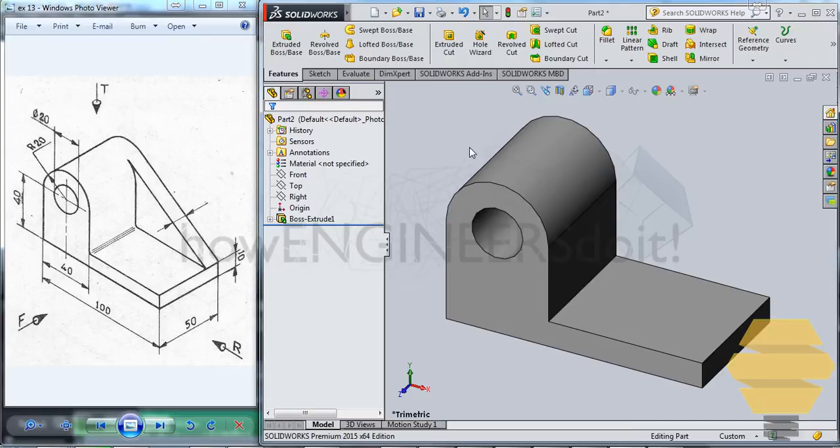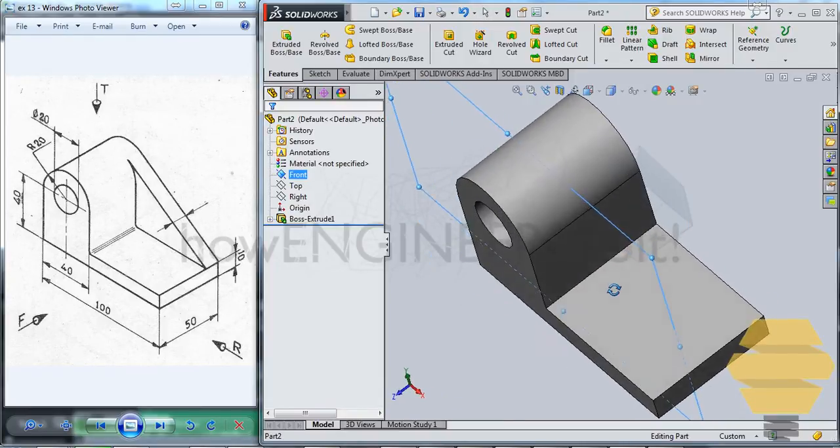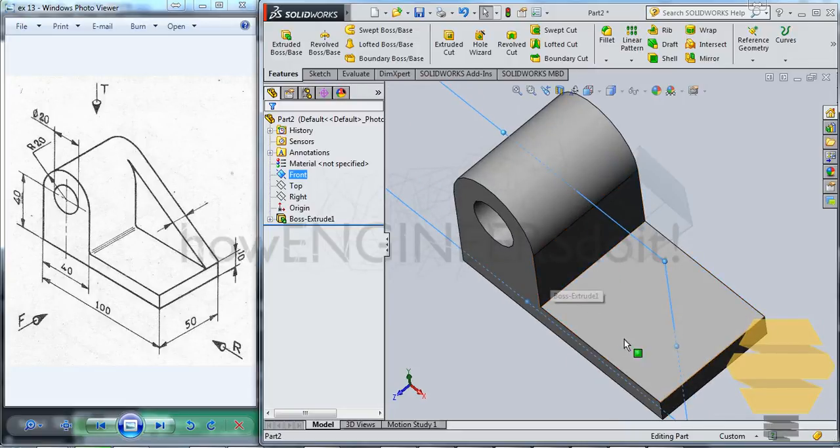And now, as I'm doing it this way, I just want to show you the benefit of keeping it symmetric. If I have to create any geometry, maybe I created some geometry here, and I would like to mirror it, I don't need to create an extra plane. The plane is already over here. That happened because I just decided to extrude on both sides symmetrically. So that's just a quick tip. Anyways, we'll continue with what we were doing.